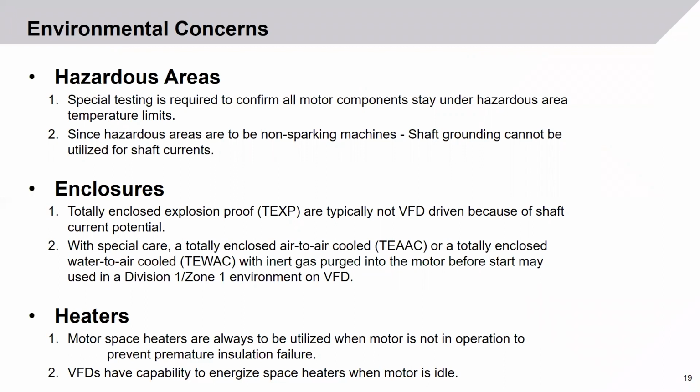So what are some environmental concerns when applying a motor on a VFD to a hazardous area? First of all, when you look at hazardous areas, specifically, let's talk about Division 2 or Zone 2 areas. Special testing is required to confirm all motor components stay under the hazardous area temperature limits for that given gas or dust. Since those areas are supposed to be built as non-sparking machines, shaft grounding cannot be utilized for shaft currents.